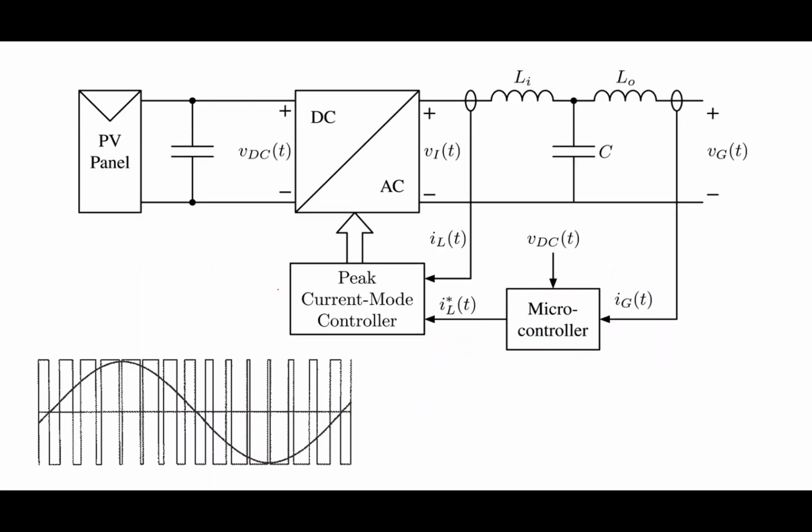This is a pretty useful thing to do, and it's very commonly used. I gave this example last time, but it's the same sort of thing. If you're doing robotics, when you drive a motor in a robot, you drive it with a square wave, and you call it a PWM, pulse width modulation. In the example I gave, a microcontroller would generate this voltage V sub I. My example here is if I had this thing I called an inverter, some circuit that could take PV. Some of you may not know what that means. Photovoltaic, so a solar panel.